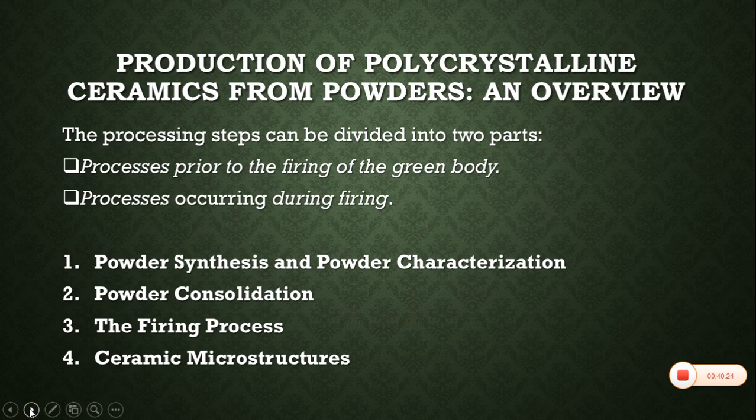During the forming methods, the powders can consolidate, which will alter the particle size and create agglomeration. So the particle size will not remain homogeneous, which will also alter the microstructure.